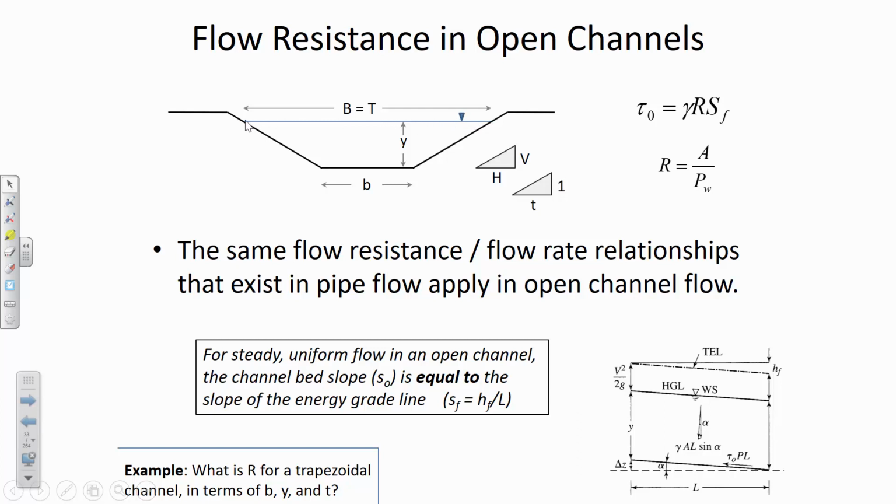So this uppercase B isn't a part of wetted perimeter. Wetted perimeter is only where the water is actually touching the solid material that's stationary. So we'd include this side angle length, the bottom width, and then the other side angle length. All right, I'm going to give you a minute to think through this. We want to know the area and wetted perimeter so we can calculate the hydraulic radius.